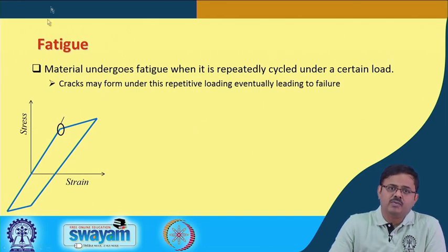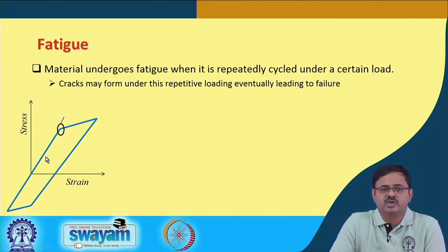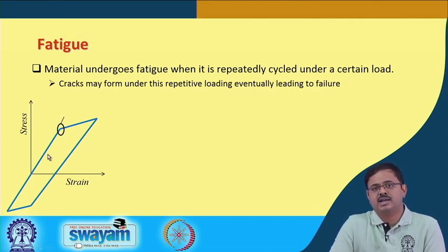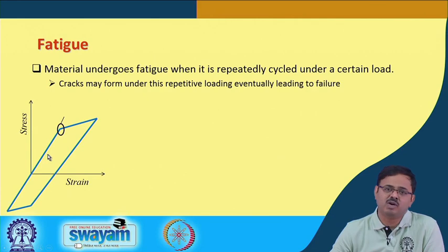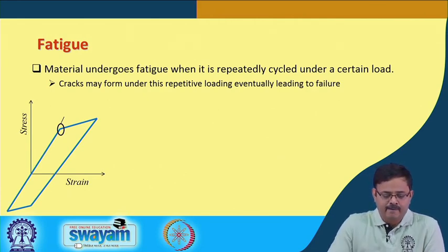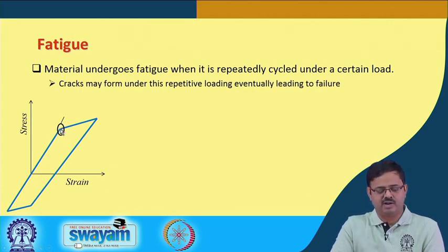Okay. So, a material we call elastic when it is in this first region, when stress is proportional to strain. The constant of proportionality is known as Young's modulus. We have all learnt it in our high school physics. So, that is elastic. But if you keep on increasing the load and therefore increasing the stress, then what happens?